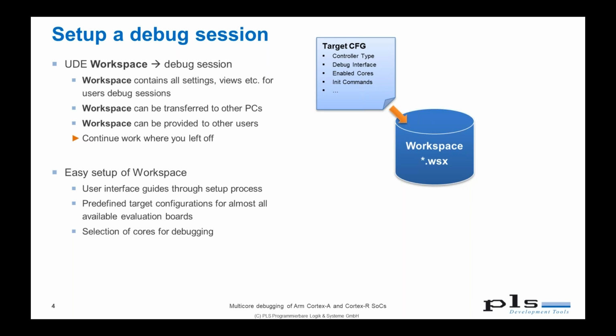Sometimes you also need to set up the target system, your controller, to be ready for debugging. Sometimes you have a watchdog which prevents you from connecting your target for a debug session or something like that.